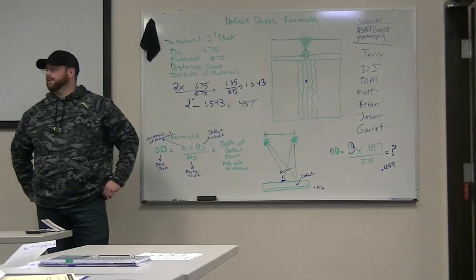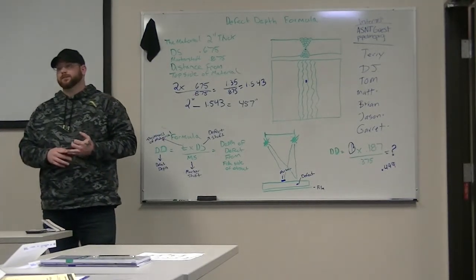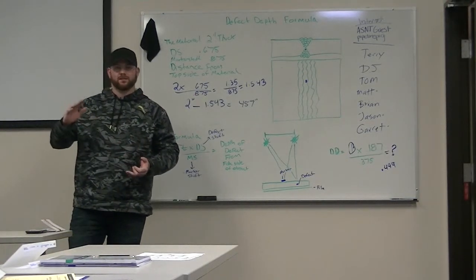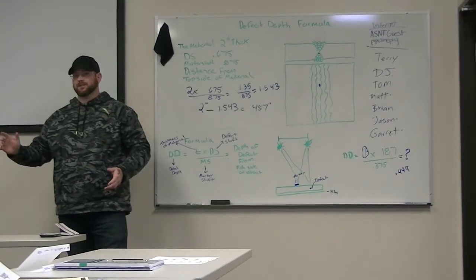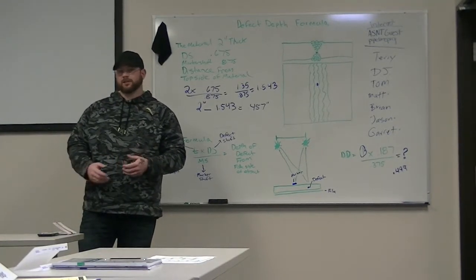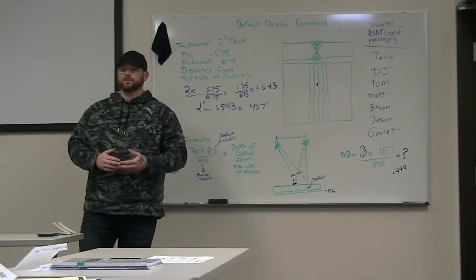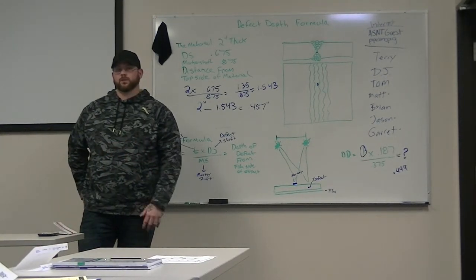But in radiography you do have to calculate your UG factor. Sometimes you might want to change your shot distance, so you have to employ a formula for changing your shot distances. Also, if you want to change the density, there's another calculation for changing the density as far as time or milliamperage exposure.